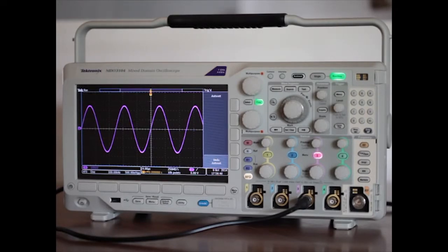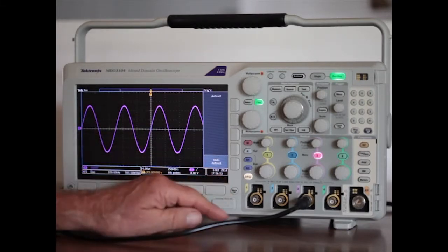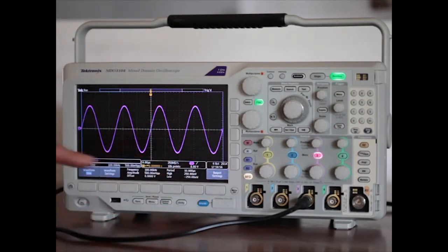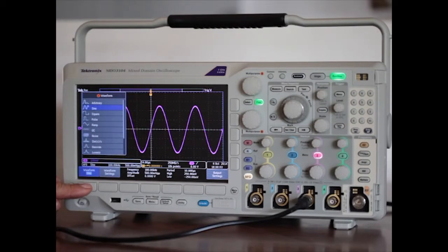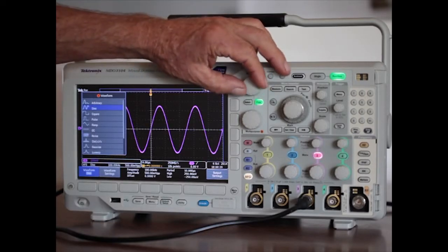The menu at the bottom of the display shows the controls for the AFG. On the left is the waveform soft key. If we push this, it shows a menu on the left with various waveforms. And as you can see by the letter at the top of the menu, it's an A, which means that it's multi-purpose knob A that will access these different waveforms.